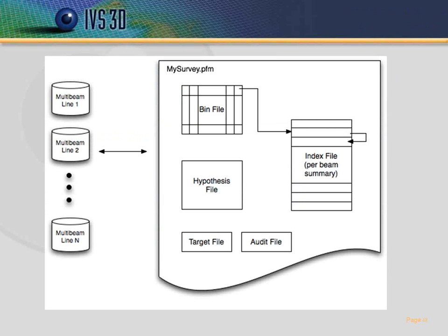This is a quick top-level diagram of a PFM. You have a whole series of source data. It usually comes from survey data, multibeam data, LiDAR data, could be lots of XYZ data. Typically, though, at its lowest level, it's X, Y, Z data, sometimes with backscatter intensities or not, sometimes with other parameters and flags to say whether the data is good, bad, or potentially bad.